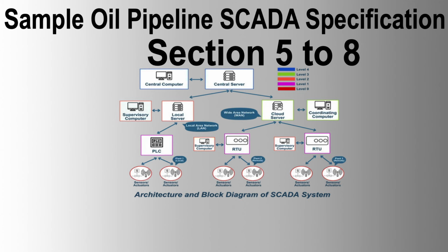8.2.4 Data Display. SCADA seller shall create mimic displays as required by Reliance. PAS shall display all inputs and outputs using SCADA MMI displays developed during the detailed functional definition stage. Displays required for calculated flow, temperature, pressure, density, and head profiles for the complete pipeline. Combination displays for calculated parameters, line plot, combined with measured parameters, bar plots. Alarm displays segregated from other SCADA system alarms where possible. System summaries, reports, batch pig tracking displays, batch scheduling displays, help mimics, leak location displays.